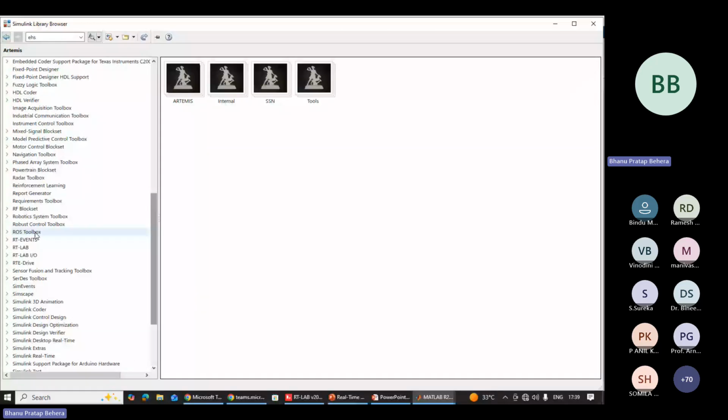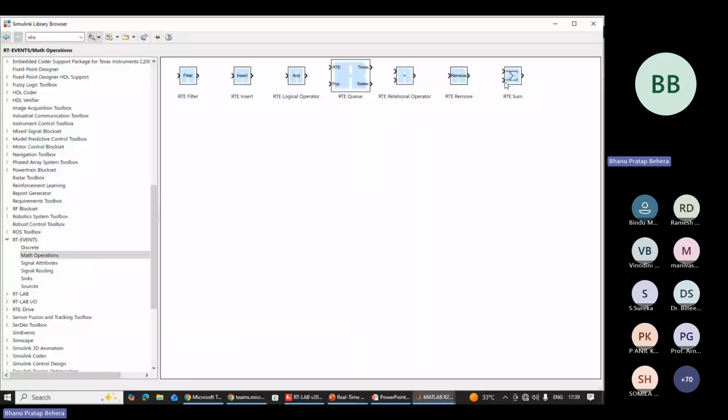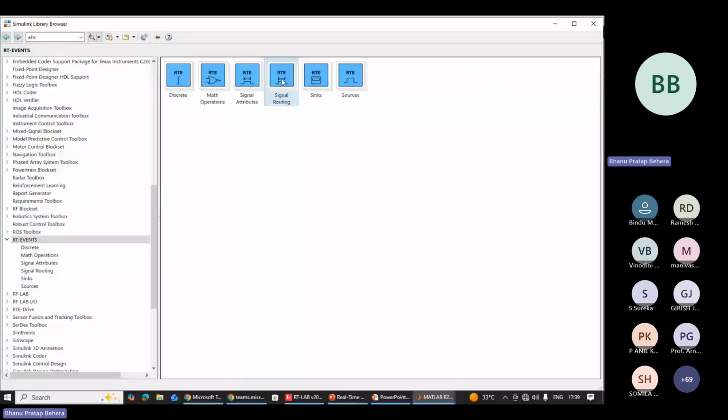These are the toolboxes used in power electronics for generating pulses, and they include logic operators, comparators, and filters. If you are using these tools, your overruns will be reduced, because these tools are specifically designed keeping in mind the requirements of OPAL-RT targets. So instead of the MATLAB toolbox, if you are using this toolbox, your overruns will finally get reduced.